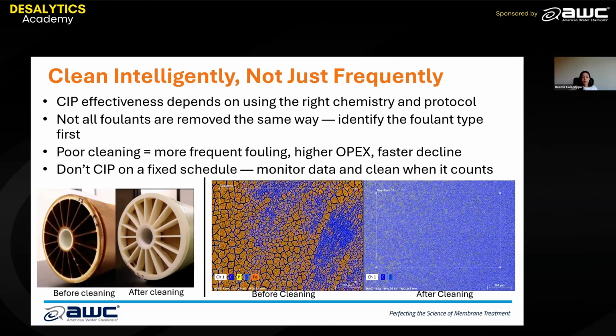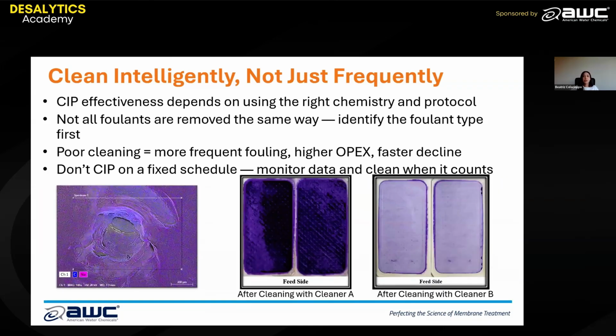So in this case, I'm just showing an example. Iron fouling is usually really common. Right here, you'd want to use a low pH cleaner. We use C217, and I'm showing before and after images of an effective cleaning. But let's say this was biofilm. I certainly would not want to use the same chemical here. For biofouling, usually we want to clean at a high pH, and depending on how severe, this is that same plant I mentioned to you guys earlier, that was overdosing SBS. And we actually had to do a cleaning study with two cleaners.